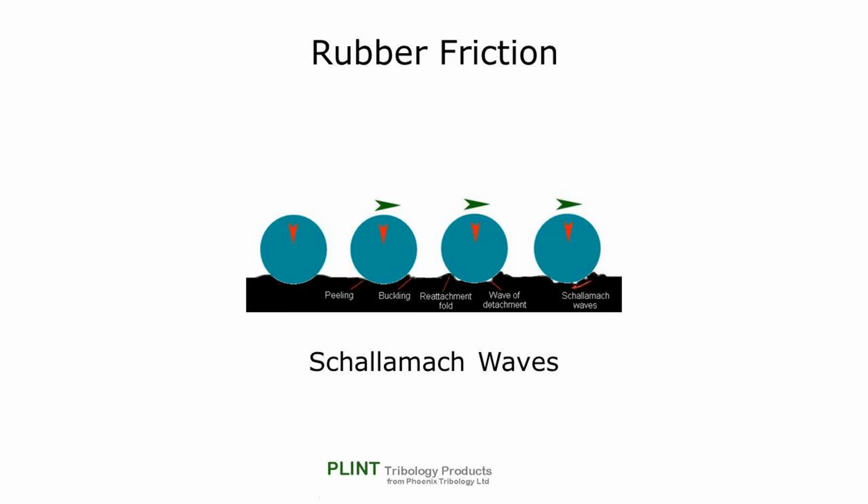The interfacial shear strength depends on the type of polymer and whether or not the surface is lubricated. These factors in turn depend on other parameters, for example the time-dependent behavior of the rubber, or in the case of liquid lubricated contacts, liquid entrainment conditions and squeeze film effects.